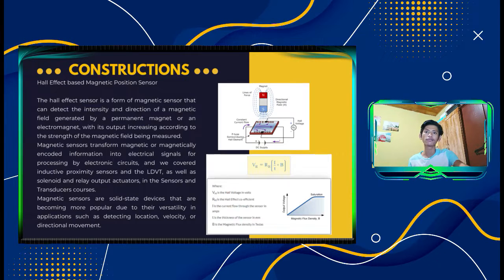And for digital output sensors, it uses a Schmitt trigger with built-in hysteresis. When the Hall sensor's magnetic flux surpasses a preset value, the device output flips from off to on without contact bounce.